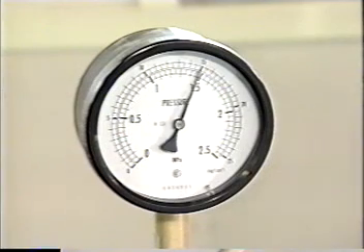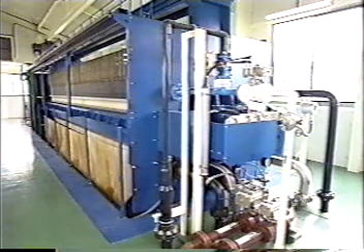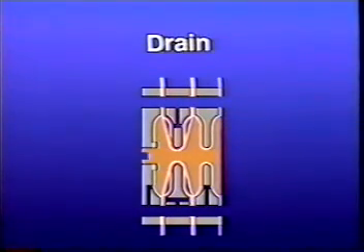At this plant, the cake is compressed for about 1 hour with a water pressure as high as 15 kilograms force per square centimeter. The compression dehydration step is time controlled. At the end of the specified time, any residual water inside the membrane is drained. At the same time, slurry remaining in the center port is blown out of the filter press.